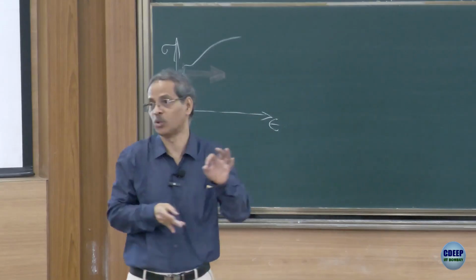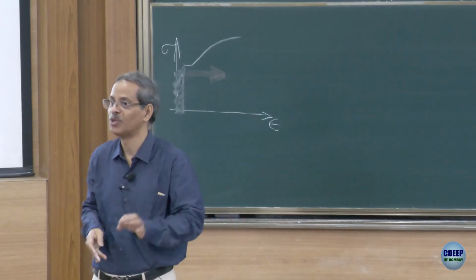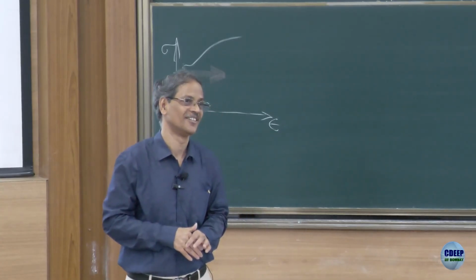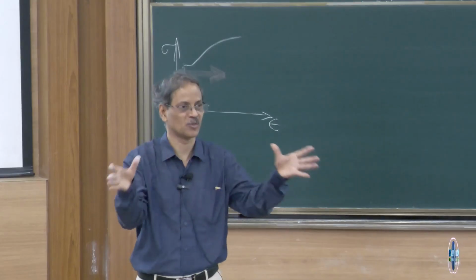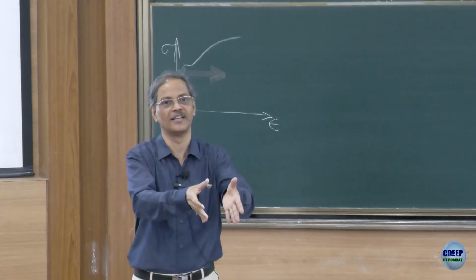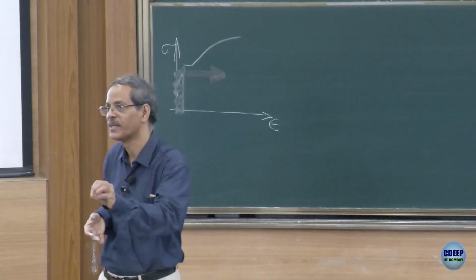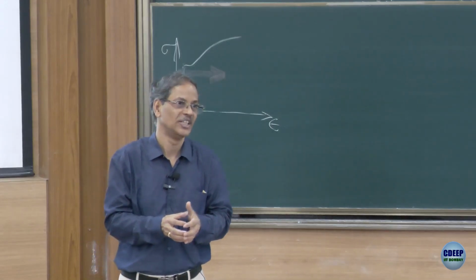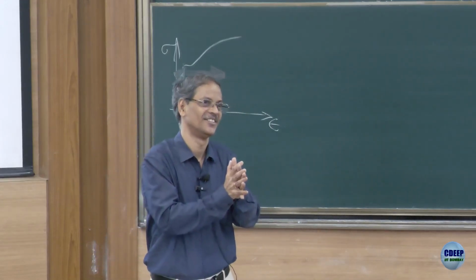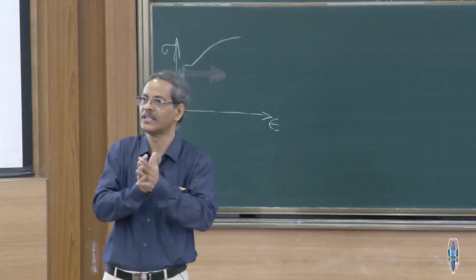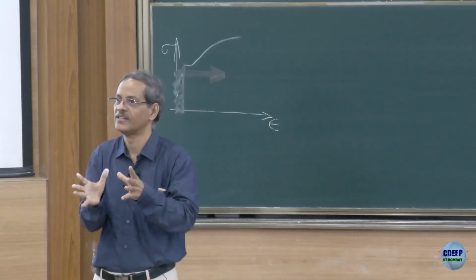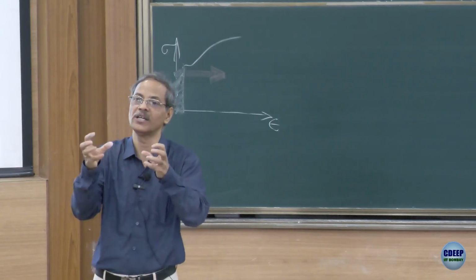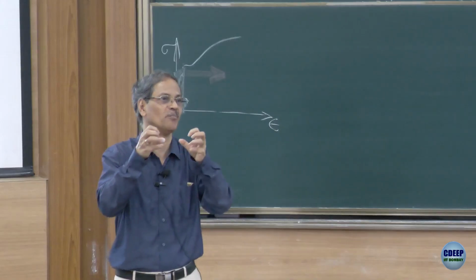We are now able to put specific features in the car design ourselves. In design, we put crumple zones, so that when a car now gets impacted, it gets crushed. We will think that it is a very severe accident, which is true, but the energy of the impact has been taken into the crushing deformation of the material.